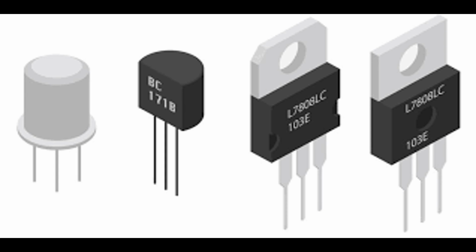Understanding the operation and characteristics of diacs is crucial for designing efficient AC power control circuits, especially those involving triacs for phase control applications. The silicon-controlled switch, SCS, is a type of thyristor similar to an SCR but with additional control features, allowing it to be both turned on and off by gate signals. This makes it more versatile and useful in various switching applications where precise control is required.